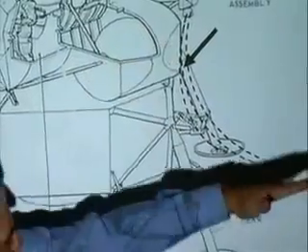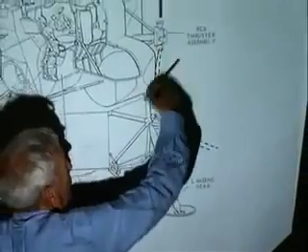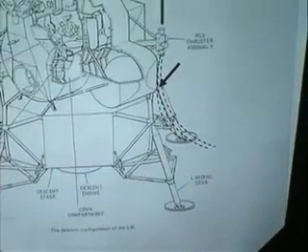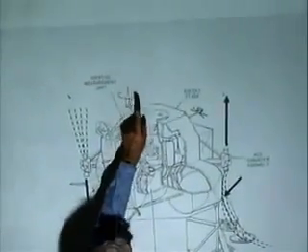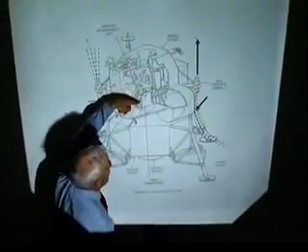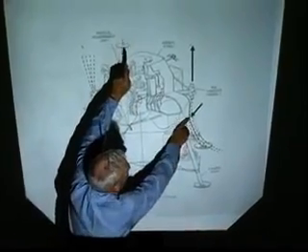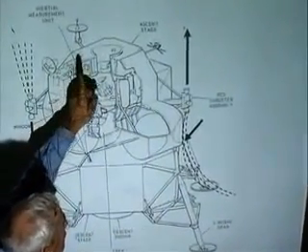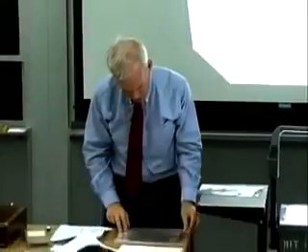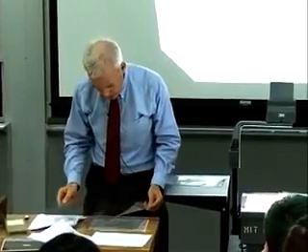And that deflection of the thrust put an adverse force on here, which is a torque in the wrong direction if the center of mass is up there. So move the center of mass from here, where you don't care so much about that, way up there, and you have to worry about whether you torque this way and get what you want, or whether you actually wind up going the wrong way. So there are a lot of reasons to be very concerned about the ability of the lunar module to control that.